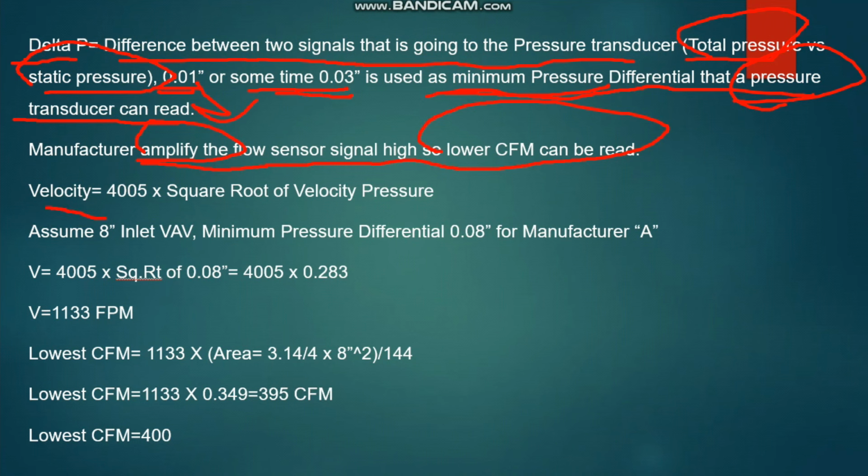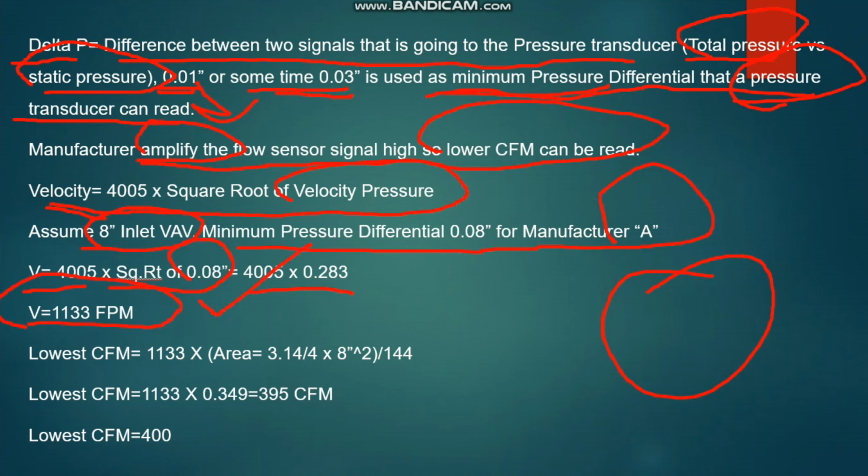So velocity is equal to 4005 times the square root of velocity pressure. This is the formula we need to know. Assume we have an 8-inch inlet VAV, the circle being the 8-inch inlet, and the minimum pressure differential is 0.08 for one manufacturer, called A. So V is equal to 4005 times the square root of 0.08 inch. We will get the answer in feet per minute. It's a velocity.